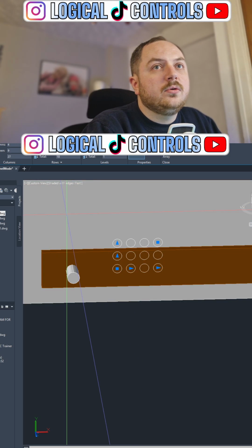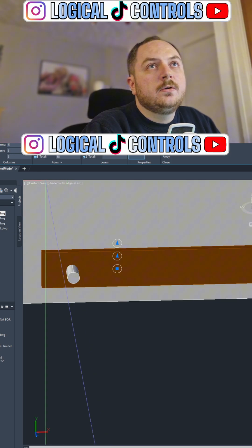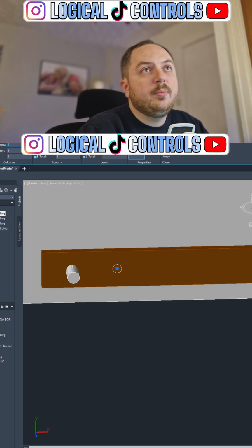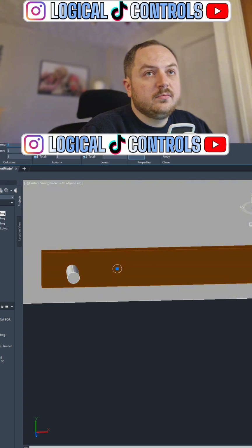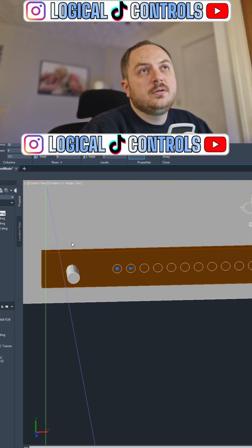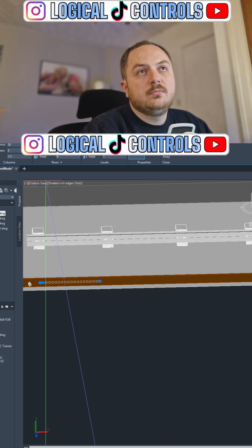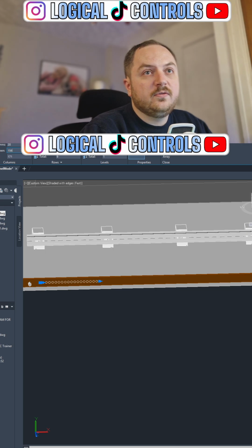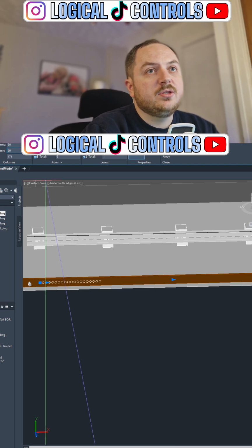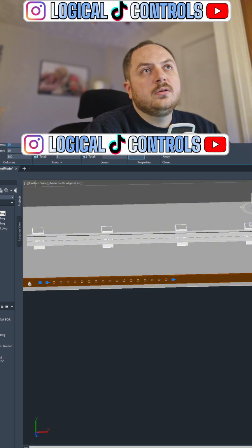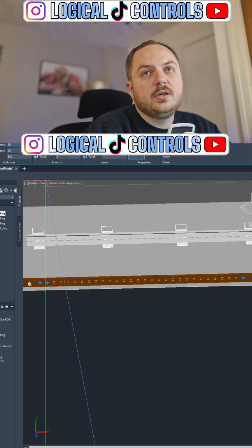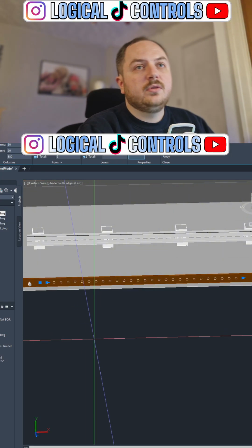I will array this so that I don't have to individually copy each one. Let's make, I don't know, 20 holes with a distance of 50, let's say 20 between them. And we can do a few more then. We can do 30 will do. Let's say 30 holes.